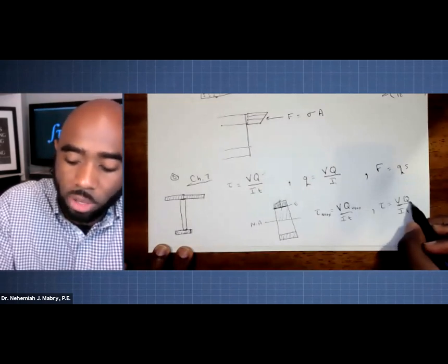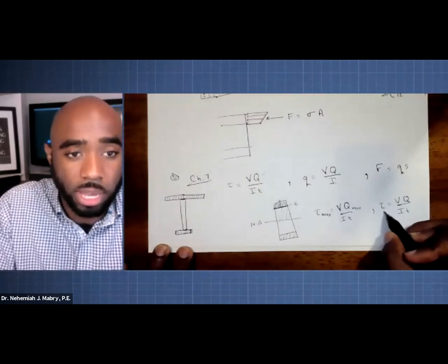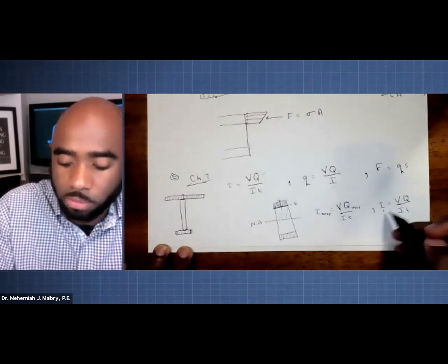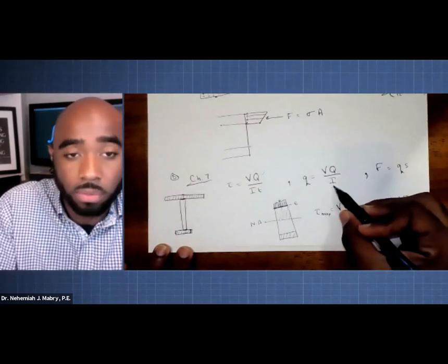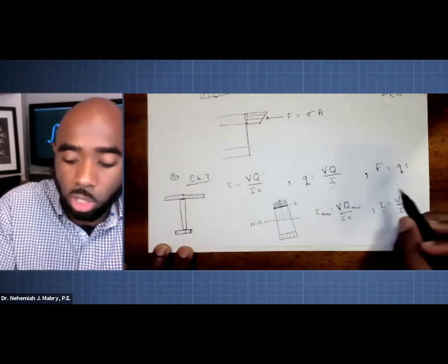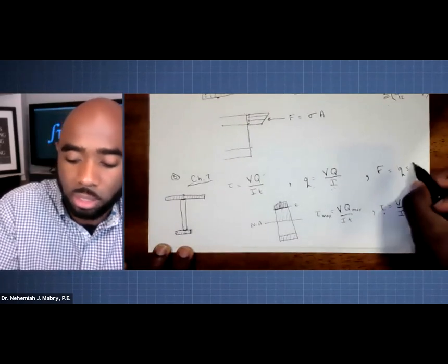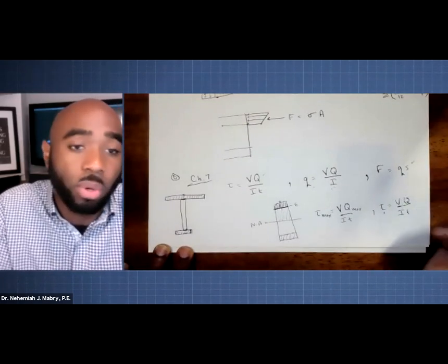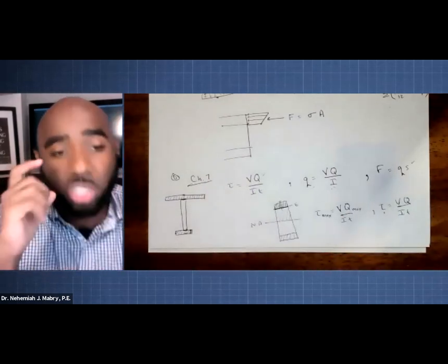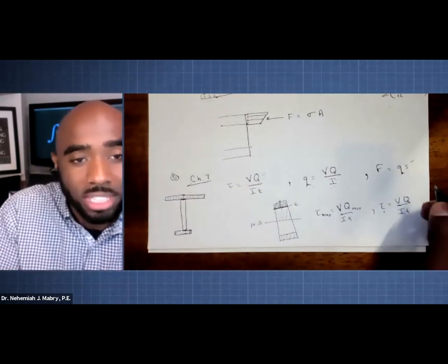You take both values for your Q. Then you'll be able to calculate two different shear flow values. You use your little q then to come over here and solve for your spacing. And if the question, as I just gave you, is asking for your maximum spacing, the answer would be whichever one gives the lowest number of S, because that's the controlling one.